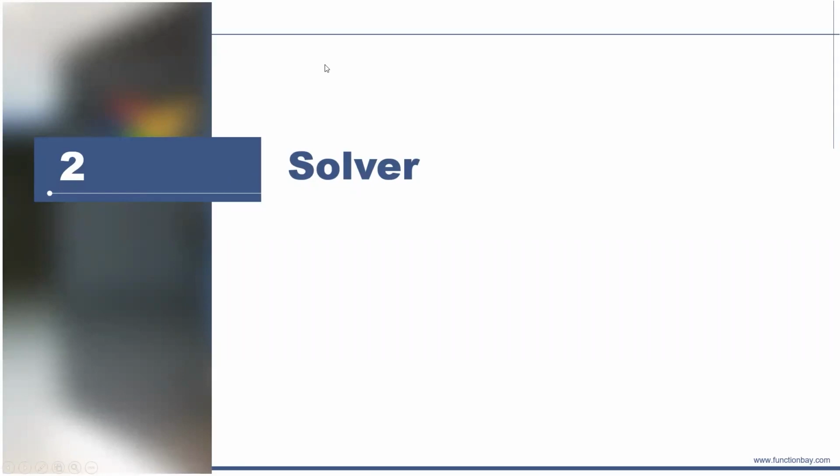So the answer to that is that there are already some analytical contact types in RecurDyn where it'll recognize primitive geometries such as cylinders, cones, and toruses, and then it automatically just uses the parameters of those shapes to perform the contact. And so there's no tessellation required. So this is something that's already in RecurDyn.